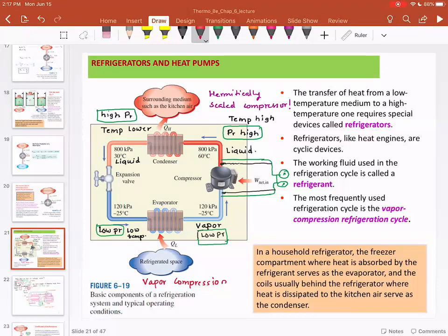So air refrigeration does not work on the ground. There could be some small supplemental vapor compression system for essential systems, but typically air refrigeration is the main source of air conditioning in aircraft. As soon as the aircraft is on the ground, the inside temperature is higher, and as the aircraft takes off and reaches cruising altitude, the air conditioning is much more efficient.